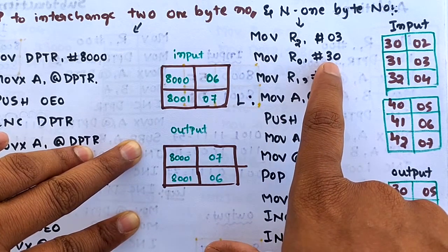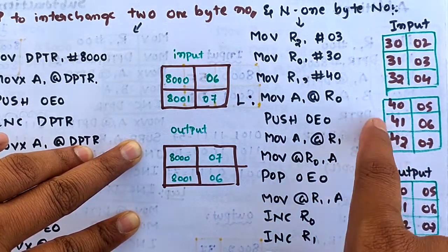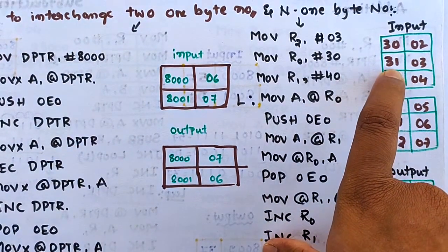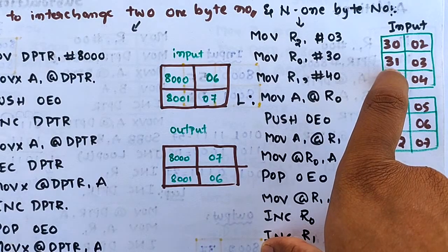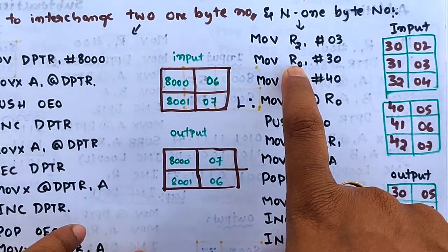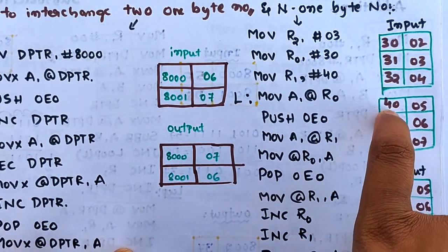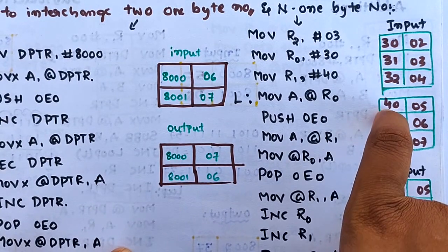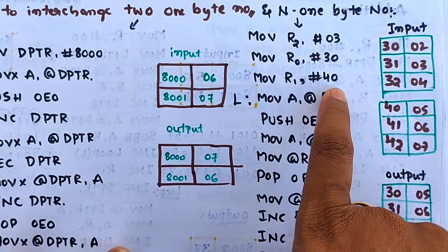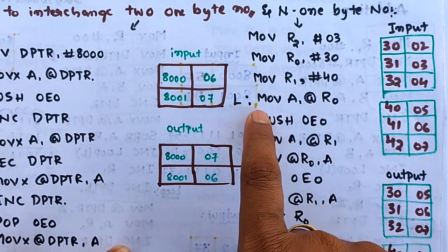So after that register, because I will directly use the internal memory location, not external memory, therefore it is an 8-byte instruction, 8-byte memory location address. Therefore I can use R0 as a pointer to locate the 30th location. At the same time I need to transfer to another location. I need one more pointer, therefore I will configure another pointer register as R1.